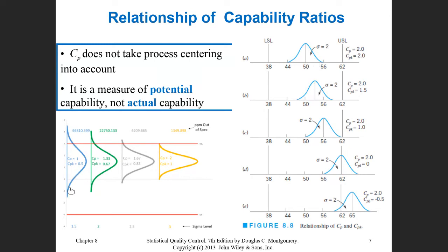The last example here in the blue distribution shows when the CP is low and the CPK is low. The process is off-centering because the center of the distribution looks shifted, as well as the variation. You see how the distribution is wider compared to the yellow distribution. That's because the CP is reduced, and that means there is an indication of high variability. So the process also is not capable.